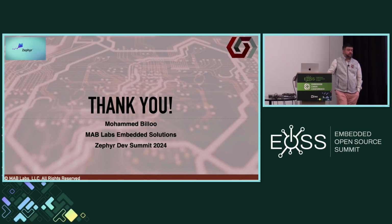Just to mention here, you can also start Zephyr with remoteproc from Linux, from U-Boot, so they can start together. But I don't have an idea right now on how to start Linux from Zephyr. Right. They can start together, like from U-Boot or Linux, you can start the Zephyr core with remoteproc. It would be interesting to see if maybe you can have an intermediary where U-Boot just sits there, waiting for the remoteproc message from the Zephyr side to say, okay, now boot.